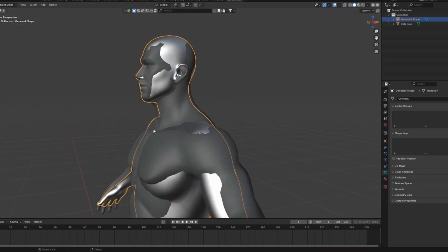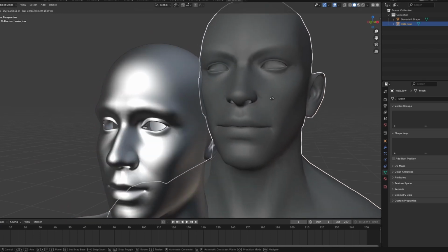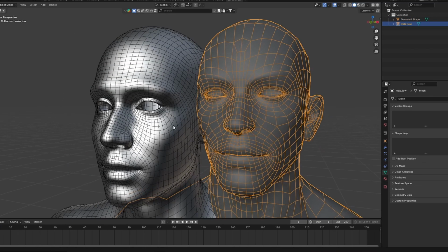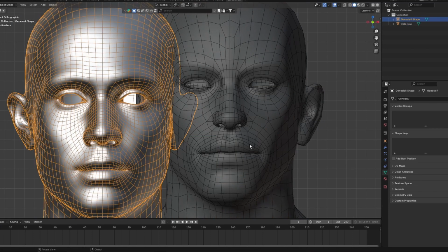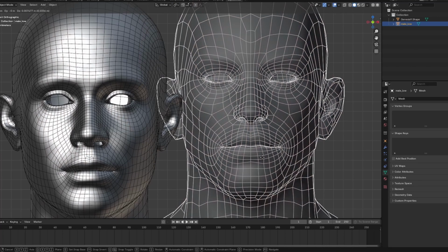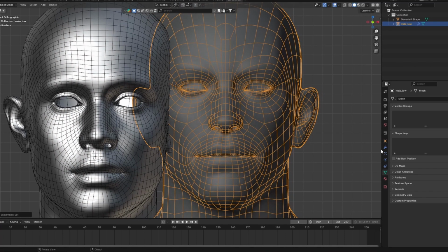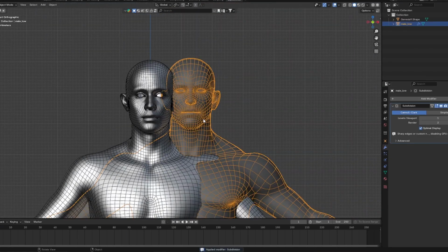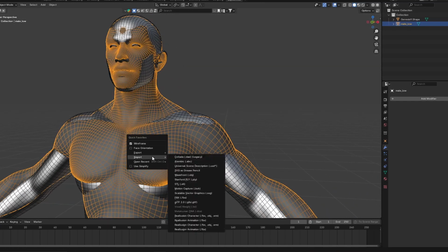So now what I'll do is I'll export the meshes out. So this is a stylized character. This is a transfer mesh, and then this is the mesh that's going to take the shape of this stylized character. If I check the wireframe, they all have good topology, but then I'll need this mesh to have a lot of resolution in order to have a smooth transfer. So I'll simply add a subdivision to it, then I'll apply. So now I have a lot of resolution on it. Cool. So I'll bring back the mesh to its original position, then I'll export it.